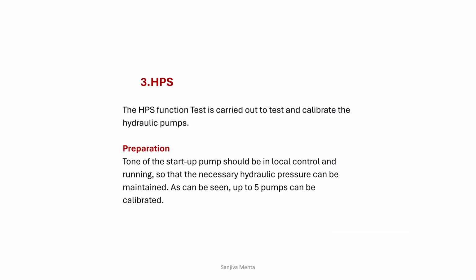HPS function test. The HPS function test is carried out to test and calibrate the hydraulic pump. The switch of the starter pump should be in local. The starter pump should be in local control and running, so that the necessary hydraulic pressure can be maintained.